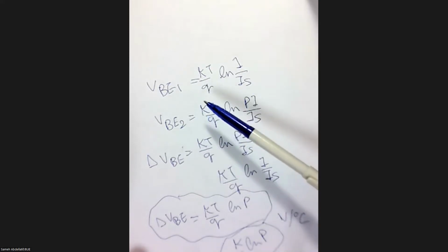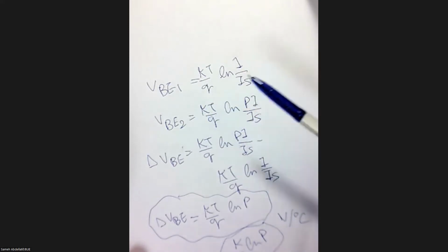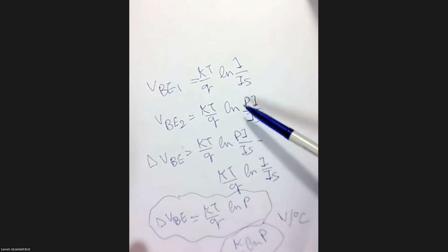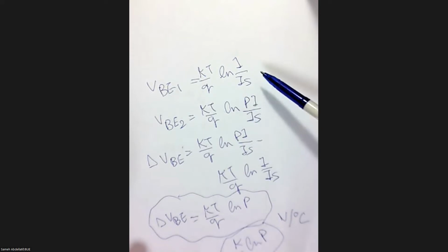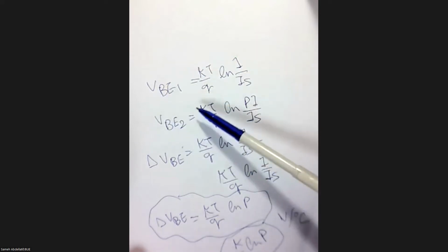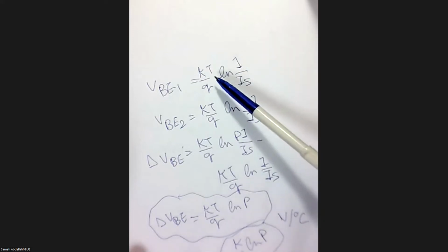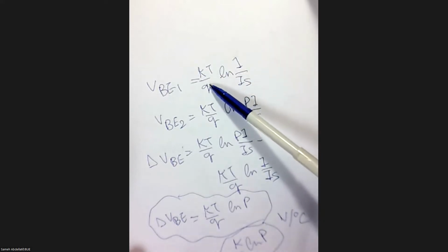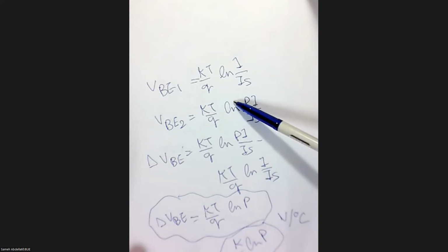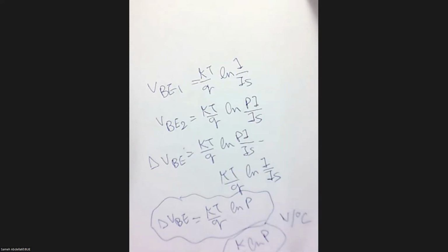However, they are not the only variable in the equation, because with the changing temperature, the current source may change and the saturation current may change as well. So changing temperature in this equation will not only be reflected by T, but also by I and IS, so that you don't have this direct relationship between VBE and temperature.